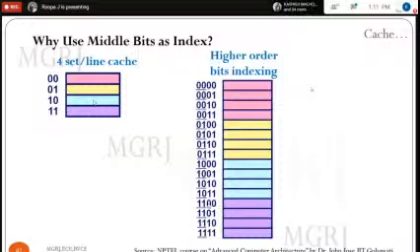Similarly, for the 1 1 address, the purple color, the remaining 4 sets are mapped to the set with 1 1 address of your cache, right? So the observation is like this: 4 continuous sets of the main memory are mapped to one set of your cache. Successive 4 sets of your main memory are mapped to one set of your cache memory according to this diagram.